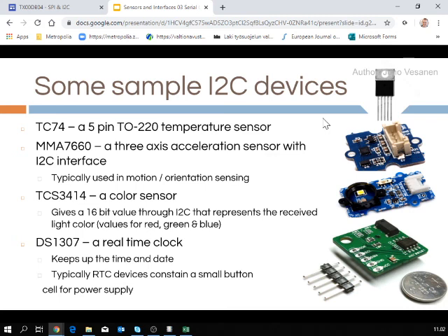Then there are, for example, I think this is originally Motorola, now I think it's Infineon, a 3-axis acceleration sensor that has I2C. It's basically that small chip here. It's one of those QFN cans, very tiny, about 3 times 3 millimeters. That's a little bit tricky of soldering, especially with these.